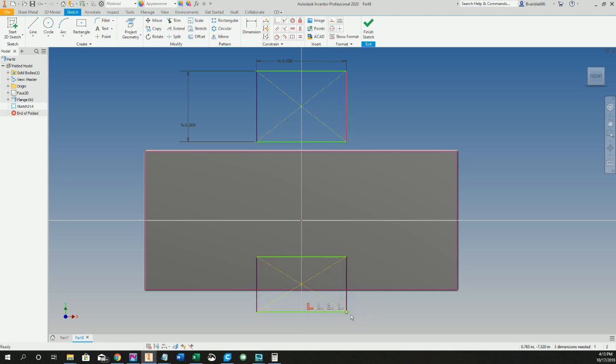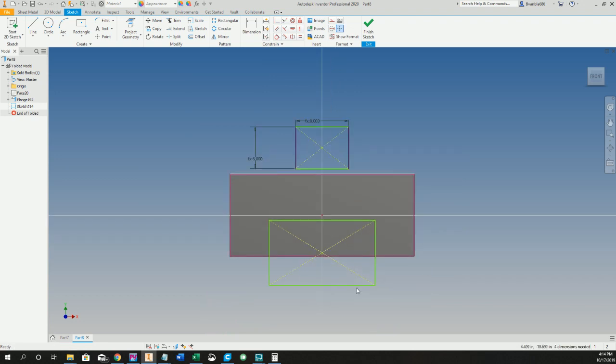Okay, so by clicking on that point, which is a real pain in the butt, it brings up all of the constraints that exist. You can see how up above, it'll turn this line red. When I highlight over the top of that constraint, I'm going to pick on it, left click, right click, and delete it. Now you see how it turned green again? Now we can resize this. That is such a pain that they do that all the time.